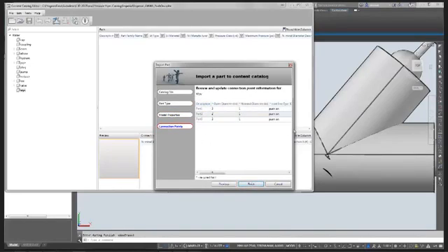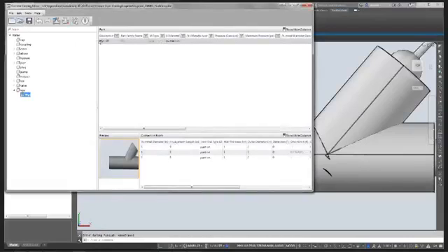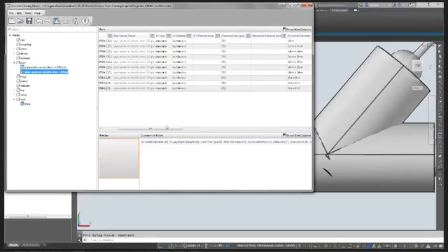Connection points, I'm going to leave them as push-ons. All look good to me. Couple of angles, positioning, just going to say finish. I now have my Y 10-inch, material is ductile iron. My schedule says DIP. I have the ability to actually use some of these blank columns for information in later details. So what I've done really quick is I've actually gone into my pipe, and I believe I did it in the 350 psi.